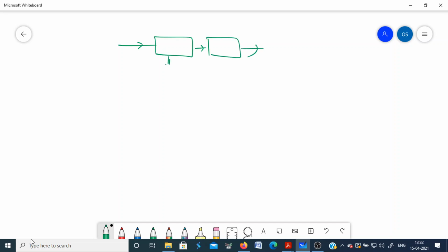The channel response, we have said, is Cn. The equalizer response is suppose Hn, and WL, the net response of this cascaded system, was the convolution between the two, which was the summation of Hk C of L minus K.